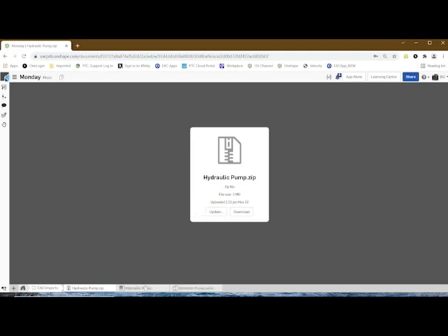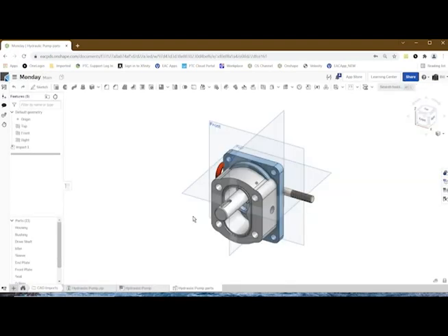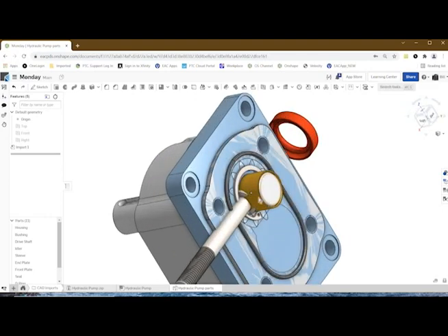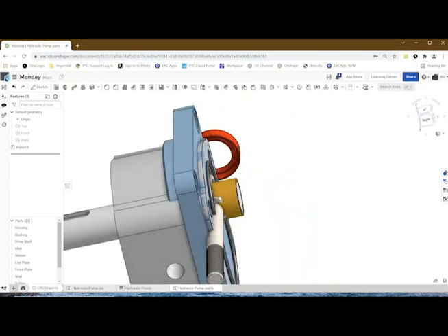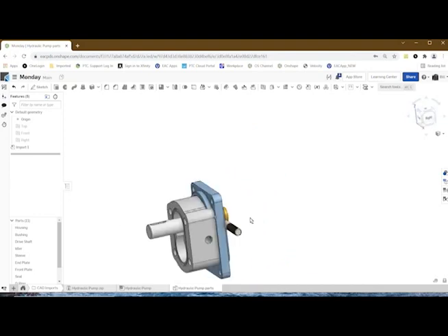So it brings those in. If we look at the PartStudio, this will be kind of interesting. We take a look at it and it's like, oh, what the heck is this? What it does is it brings in every part the way that it was created at 0, 0. So you can see all these parts were created at the origin, except for this guy. He's probably made in the assembly, so that's why he's over here. But the thing is that only the unique parts come in. You notice there's only a single bolt here. There's only a single sleeve here. So it only brings in the unique parts.